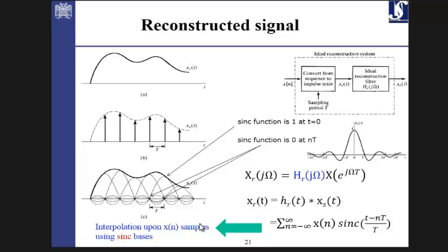So you have the sinc function at t0 and t, and they are summed up together. So it means that in general, the complete reconstruction is not possible, and definitely you will have a kind of error here. There was an error in the beginning, quantization error, and there is an error in the end because of the sinc function error.